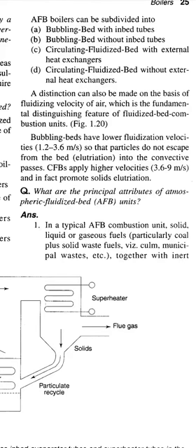CFBs apply higher velocities, 3.6 to 9 meters per second, and in fact promote solid entrainment. Next question. What are the principal attributes of atmospheric fluidized bed units?